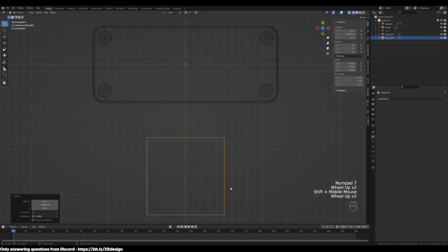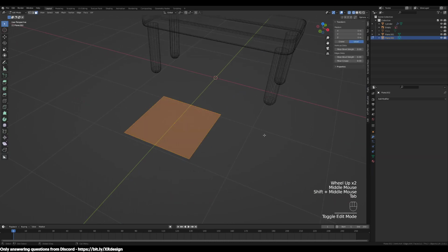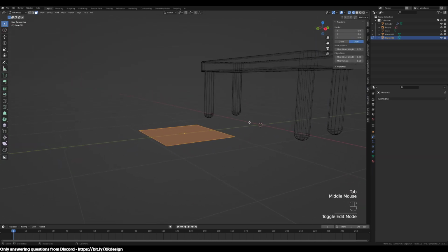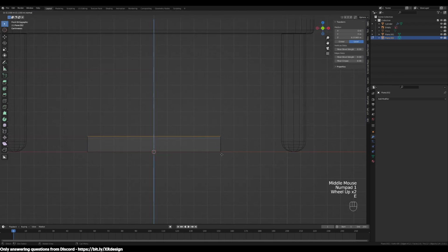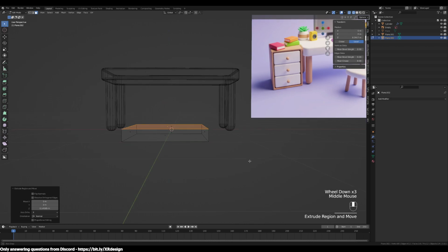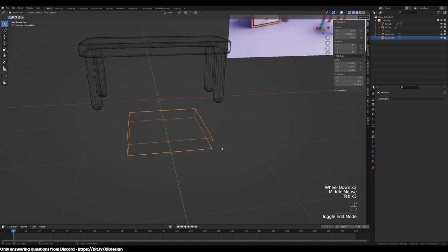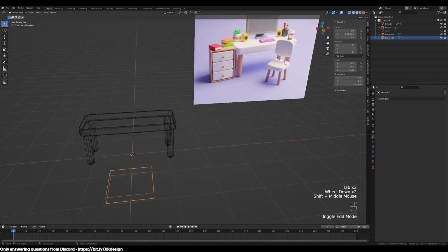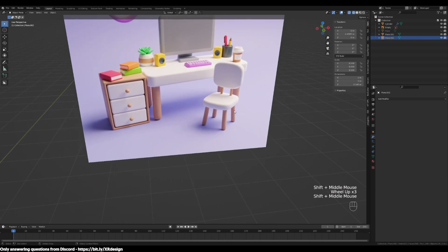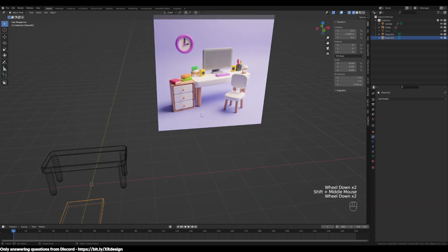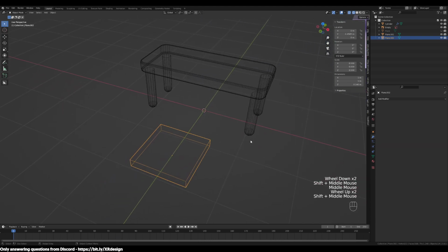And then let's go into edit mode, extrude it by, let's say 1.5 of these smaller units, maybe a little bit less. And then for this object itself, it's not perfectly square, so it's not like a perfect rounded corner, and I wanted to do that intentionally.